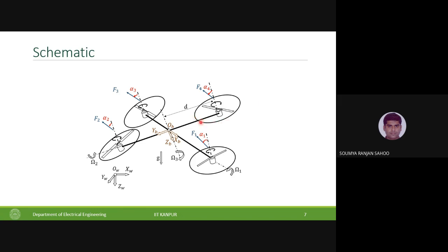How do you do that? The vertical component is controlled by this angle, and in addition it can also be controlled by the speed of the rotor. Of course, if you change the speed, the horizontal component also changes. So it's a combination of the speed of the rotor and the angle made by the force vectors that generates a sufficient horizontal force and a sufficient vertical force to meet your desired translation and desired attitude commands.